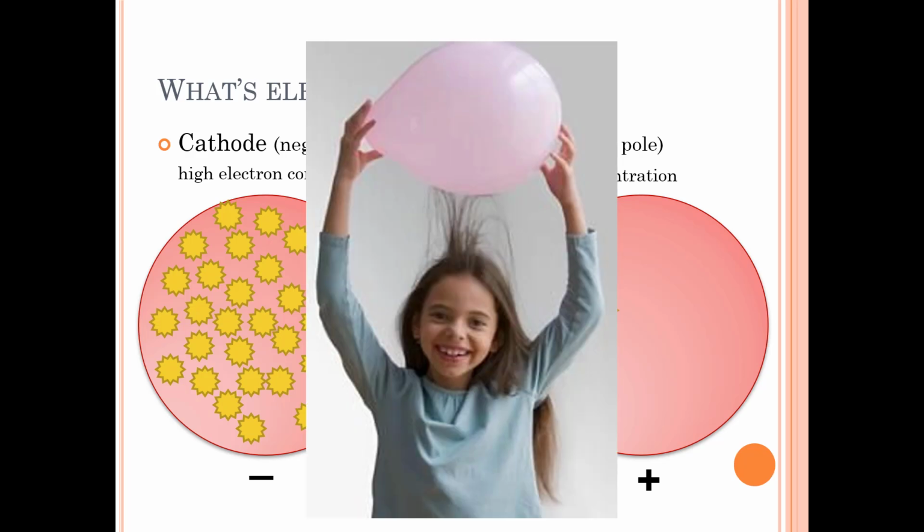Static electricity can be stored in an insulated conductor in which the charges are in a state of tension, ready to flow. The discharge is often a single discharge, into the ground or through something else and into the ground. The body of Earth is considered to be an electrical sink, which means that it can accept or supply any reasonable amount of charge without changing its electrical characteristics.